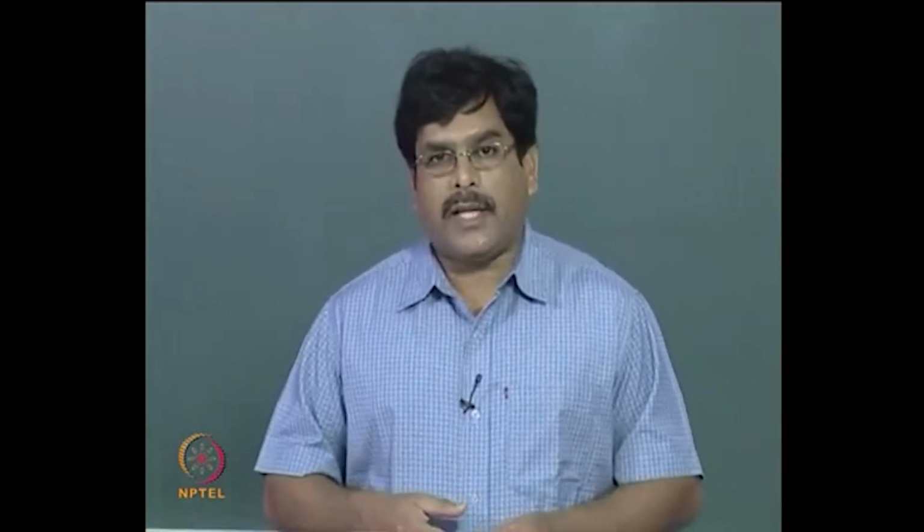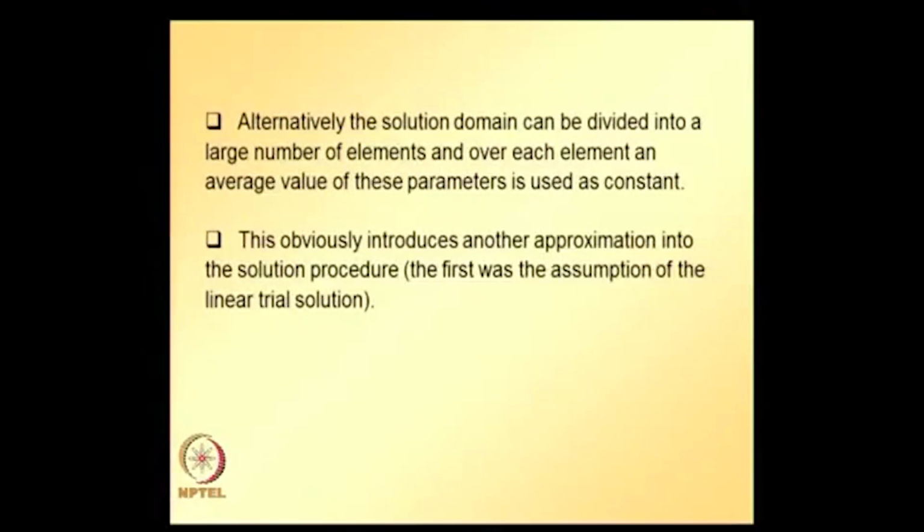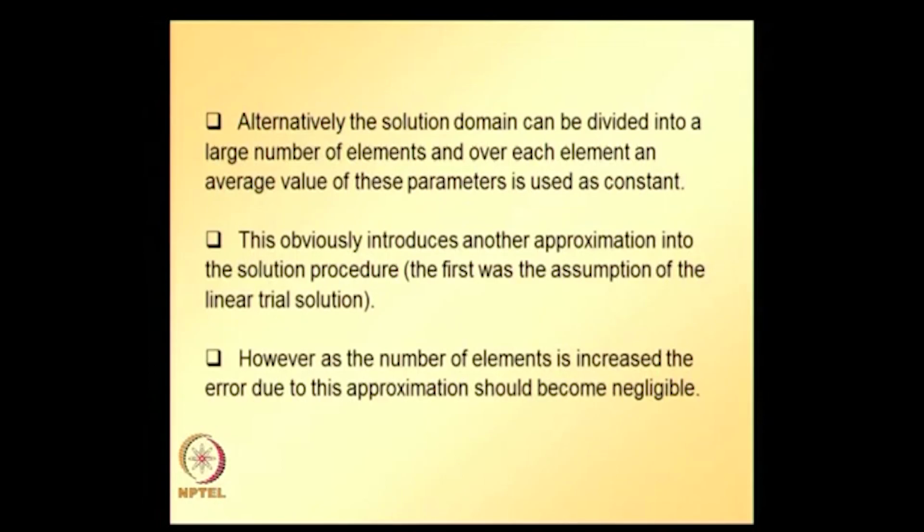For a specific problem related to any application, we need to identify what these coefficients k, p, q are, and from the boundary conditions we can identify the alphas and betas, and we can directly plug into the element equations that we derived based on linear finite element approximation, and get the element equations for the corresponding problem, which will be very advantageous.